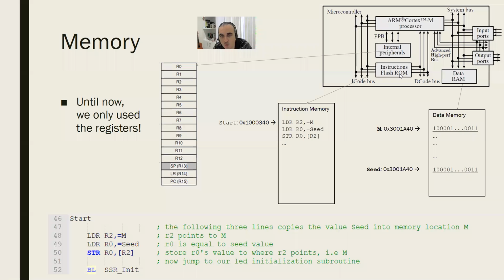We have another memory type, because this type of memory cell is not called the memory, they are called the registers. They are called the internal peripherals, but they are like memory because you can keep information in them. Some registers you cannot write directly, they are flags, you read them, but some of them are scratch paper registers. They are for you to use and to do your arithmetic operations, but they are not called memory because memory is something more general.